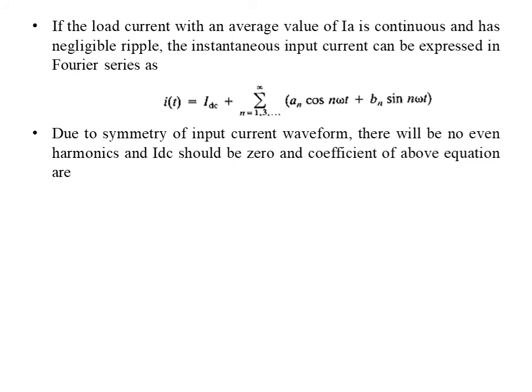Due to the symmetry of the input current waveform, there will be no even harmonics and the DC current, that is I_DC, should be 0.